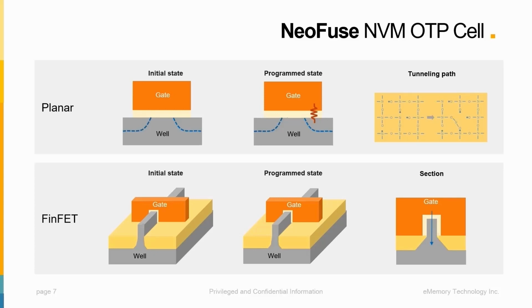On the other hand, if the memory unit has not been programmed, there will be no quantum tunneling path inside the oxide region. Therefore, no current will be collected at the source or drain terminal, and we will define this state as digital 1. In terms of data preservation ability, using quantum tunneling path inside the oxide layer has been tested and verified to prove it can endure various environmental conditions, such as high temperature and radiation. Furthermore, the program path is guaranteed to last for more than a decade inside the oxide layer, showing excellent longevity in its data storage capability.